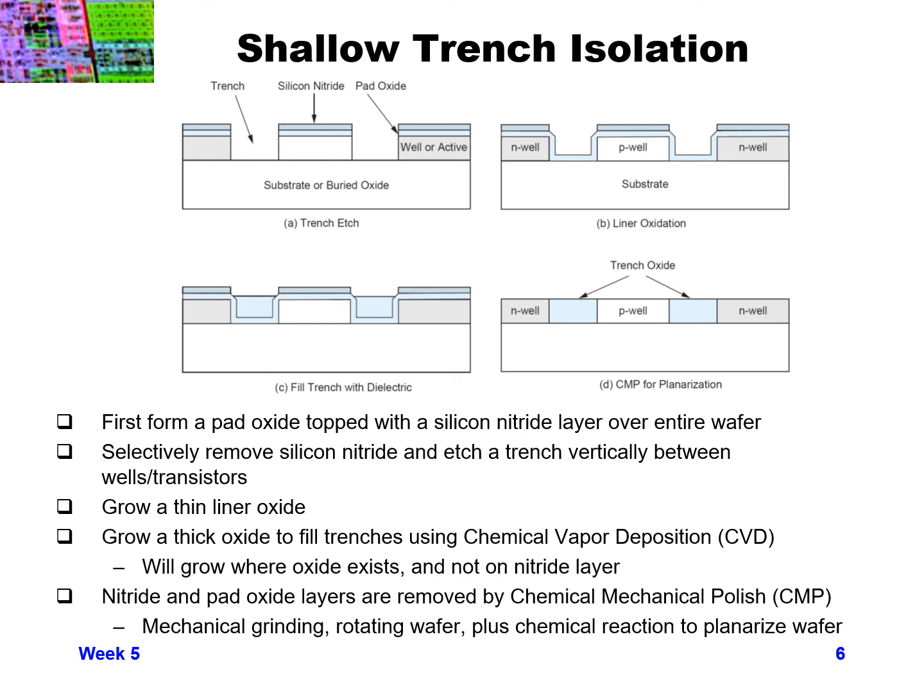And the chemicals that we'll use in this CVD step will only grow, they'll react and selectively grow on existing oxide, but they won't grow on the silicon nitride. And so we will grow an oxide layer inside the trenches, but not on the rest of the wafer where it's protected by the silicon nitride. So then that fills the trench with a silicon oxide dielectric, which is step C shown in the figure.